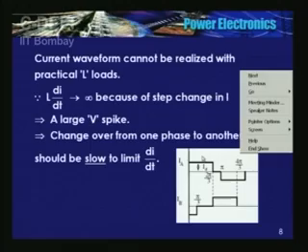What happened in the voltage source inverter? In fact, we had used very fast devices. We wanted almost instantaneous changeover from one device to another device. Load may be inductive. Why here do we need to have a gradual fall and gradual rise? Reason is very simple. The freewheeling diodes take care of this inductive energy.